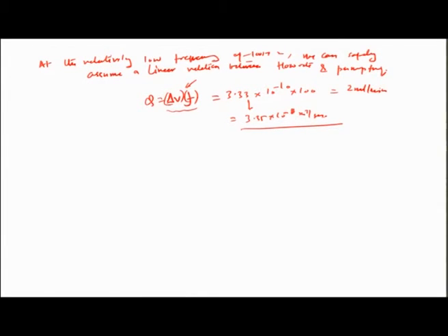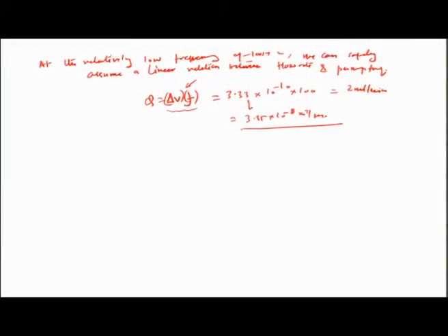So, that is how you compute how a peristaltic pump, through a certain actuation which is made again in electrical manner, would be able to give a certain flow delivery against atmospheric pressure. So, that is how actuator design for peristaltic micro pumps can happen. I would also like to give another non-conventional or non-mechanical micropump concept, which is based on the Marangoni effect, the thermocapillary effect.